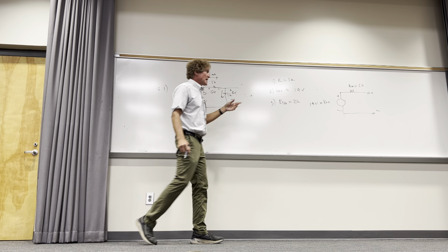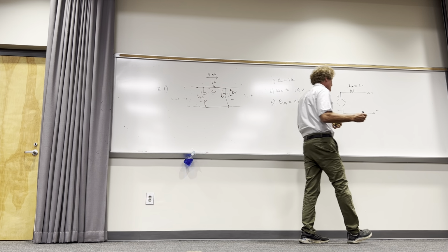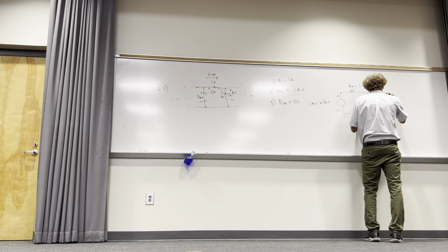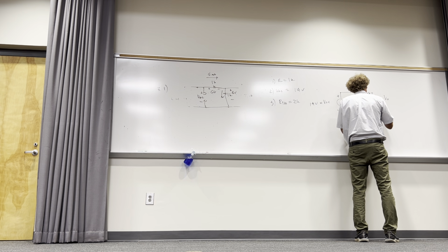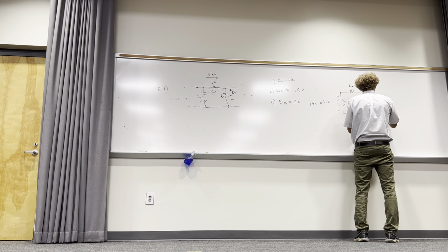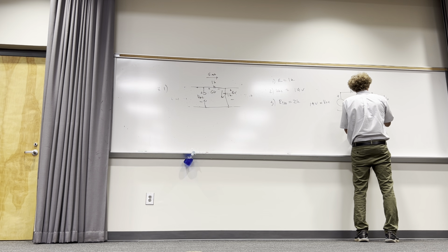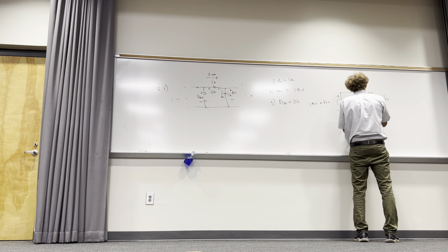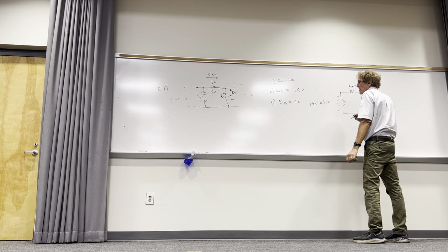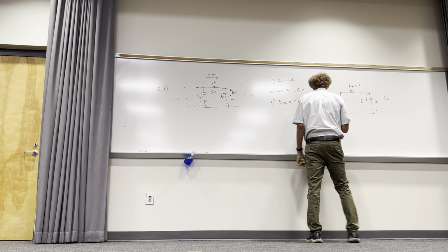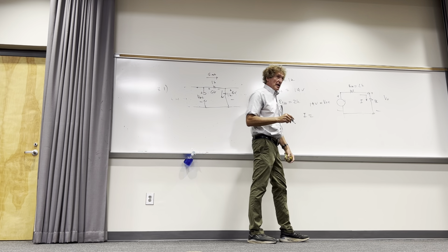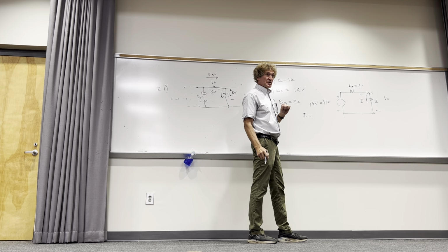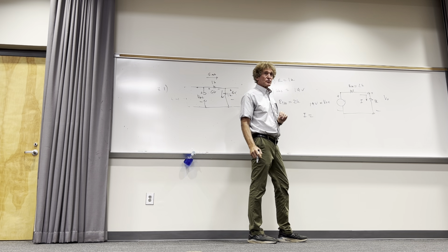Very easily. Now, the next step is this is where the load voltage would be, or V out, and the current. Now I put the resistance back in, and that resistance is 1K. And in this case, they wanted the current through there. What would that current be? I think you can all see this by this point. It's really going to be just VOC divided by R Thevenin plus 1K, right?